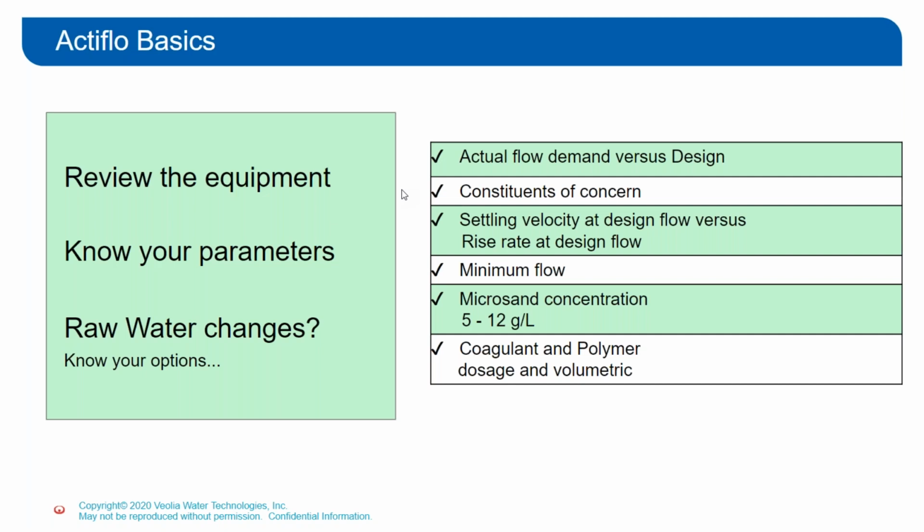You have more static mixing, more easy, gentle maturation time, natural mixing of the primary particles with the coagulant and polymer, as compared to a mixer, which can shear the particles, especially if you're dealing with an anionic flock or something that is a little bit more fragile flock formed. But there's also a minimum flow, even if you're not just trying to crank one to get a good process chemistry.